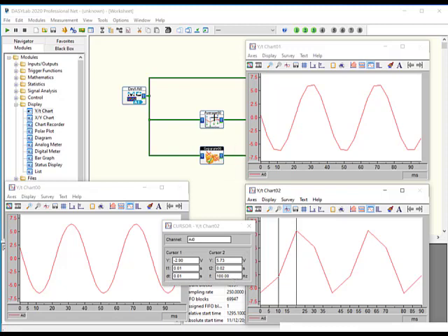So we averaged to 250 hertz. We separated down to 100 hertz, and we're looking at the same interval on the screen. We're still looking at 100 milliseconds worth of data. We're just seeing fewer samples in all of that data. So this is a way to reduce the total amount of data. Again, it's going to depend on whether you need to retain your waveform, in which case you would probably use average, or you just simply want to reduce the total amount of data without changing the maxima and the minima of your signal.